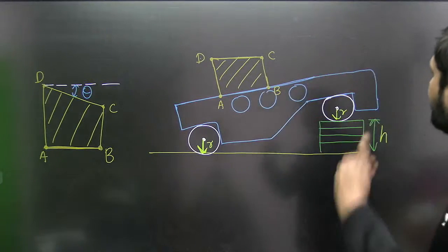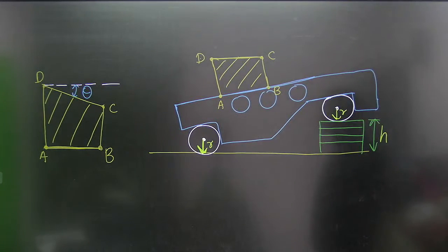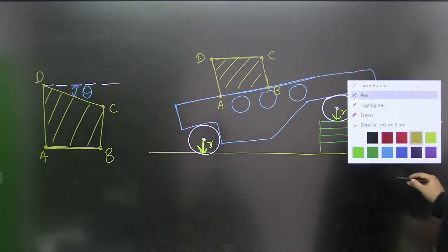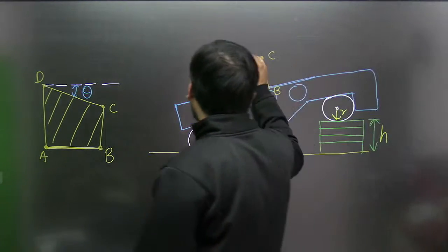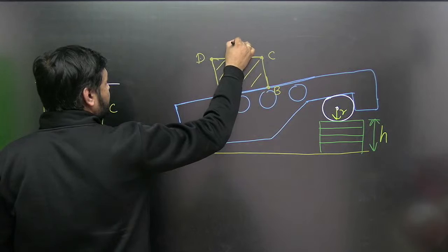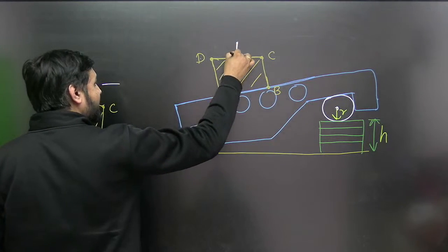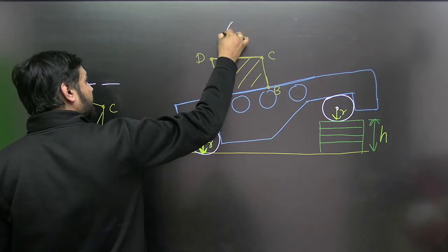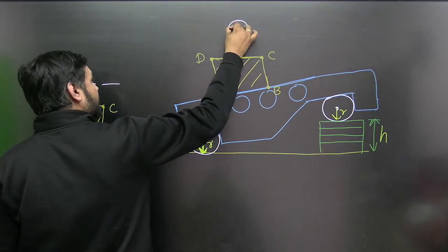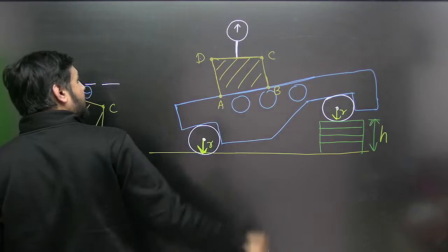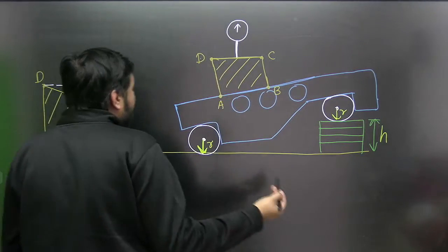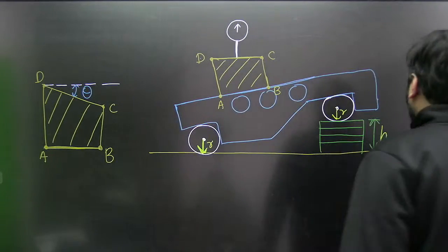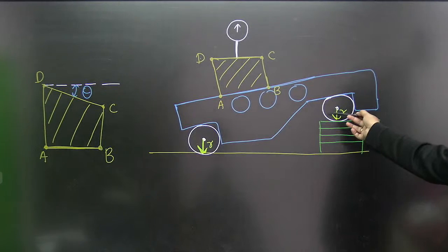And above that wedge-shaped block, my dear lovely students, there will be this dial gauge. The dial gauge will have its pointer resting on the top surface of this wedge-shaped block. We'll be piling a certain number of slip gauge blocks over here.